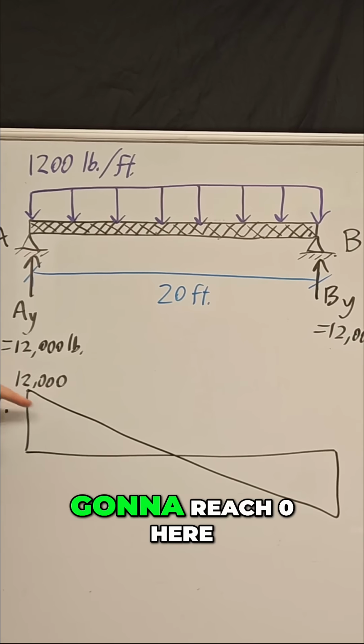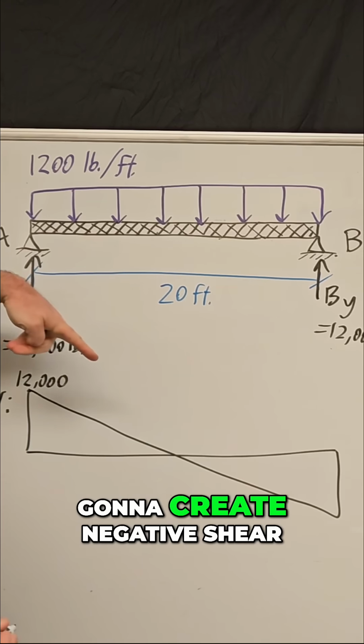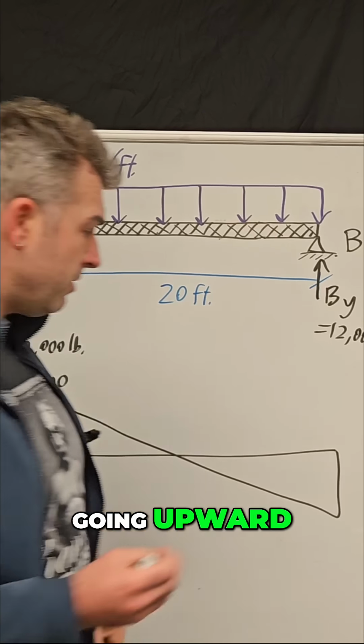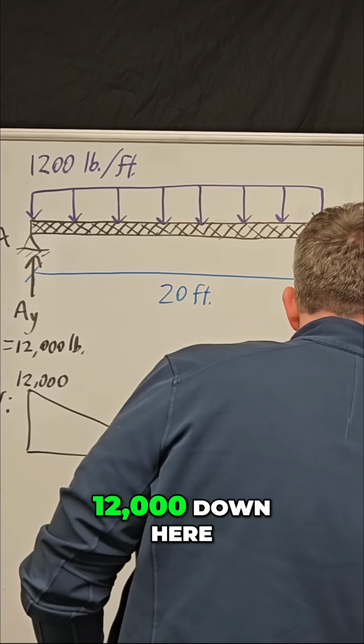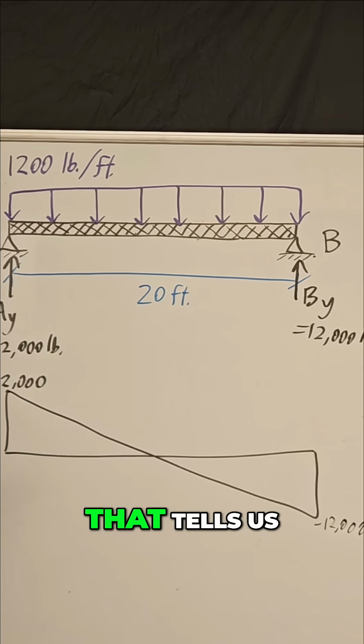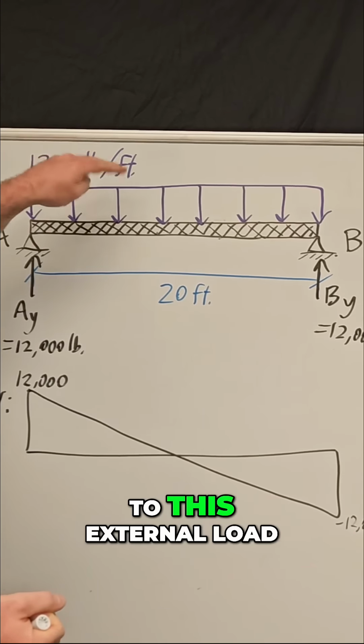And at some point it's going to reach zero here right in the center of the beam. And then that downward force is going to create negative shear in the beam. And then at the end we have a 12,000 pound force going upward. So I'll label this as negative 12,000 down here. And so that's our shear diagram. That tells us how much internal shear force the beam is experiencing due to this external load.